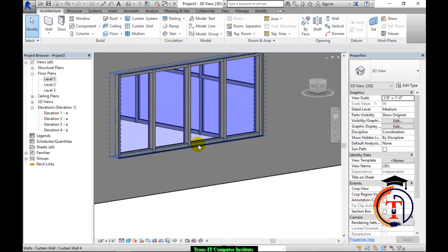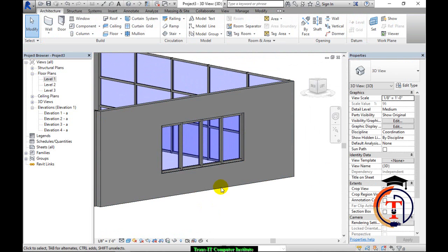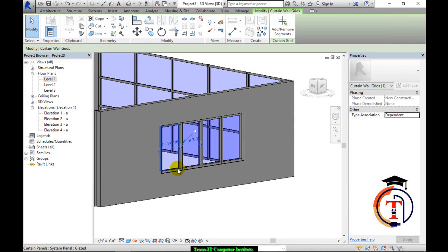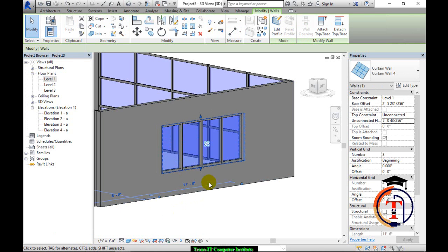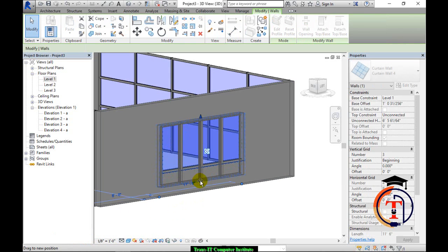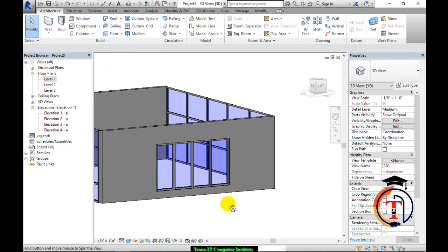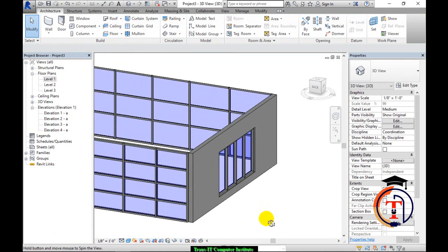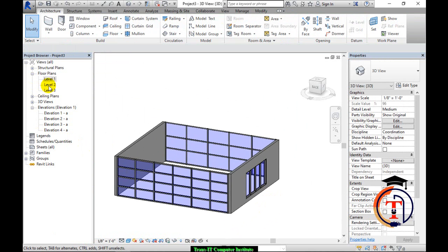Okay, so it is a French window type that I have to show, so hardly there will be a gap of 6 feet at the bottom. Press Tab and look. When selecting a wall, if there is a problem, always use Tab. Okay, so here I click on the wall. Then again, clicking here and taking it down, you may show it as your sliding window. Now there is another trick over here.